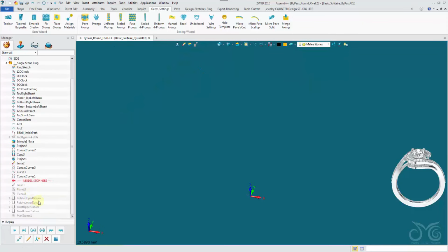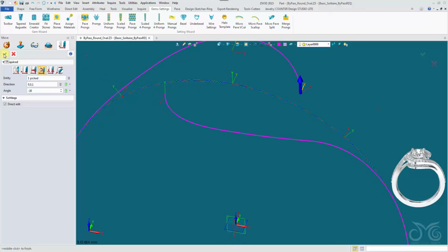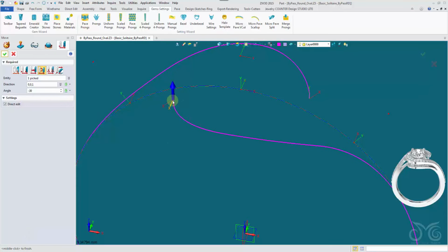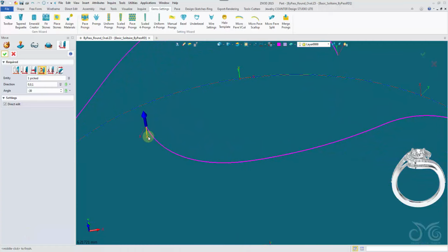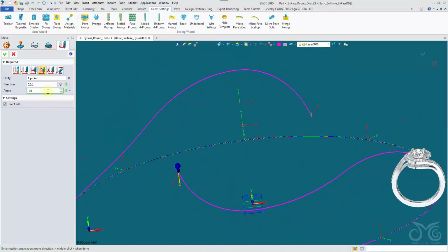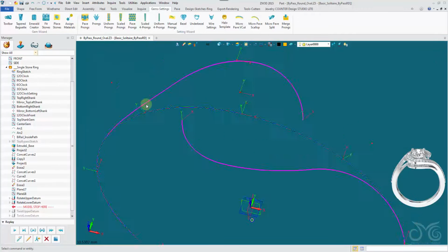It's going to be one of these controls here. If I drag my model stop up, I can edit one to see what it is controlling. Okay, so this is the rotate upper datum, this one, so I'm guessing I want the rotate lower datum. And I do, so we're rotating a -30. But I will want this to be on the opposite side, so I'm going to add 180 degrees to this rotation. So I'm just going to do a plus sign, 180 degrees. Now we have that X in the correct orientation for us.